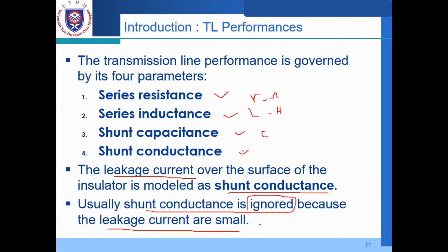So basically there is no shunt conductance, and later in the short line model we will see that shunt capacitance is also being neglected. So this is particularly for short distance, the short line.